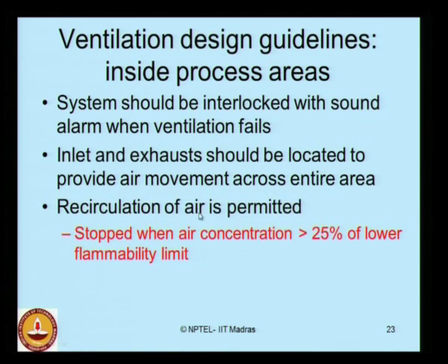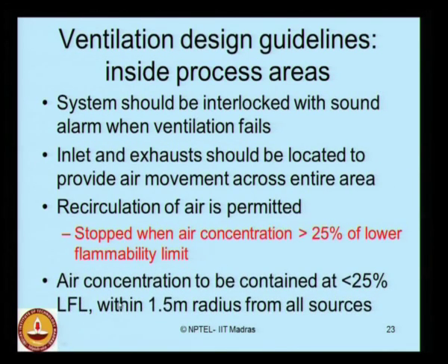The recirculation of air is permitted, and it is stopped when the air concentration exceeds 25% of the lower flammability limit. In addition to that, the air concentration should be contained below 25% of LFL. This is a very important requirement of the design guideline for the process areas, which is different from that of the storage areas.